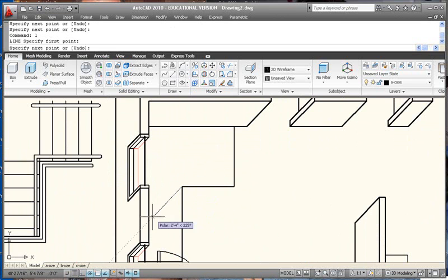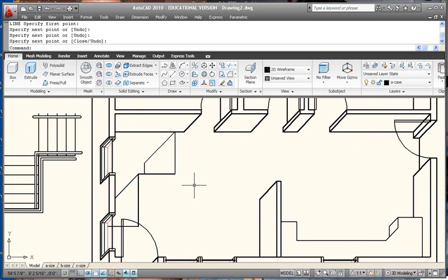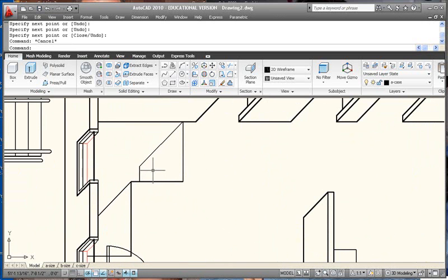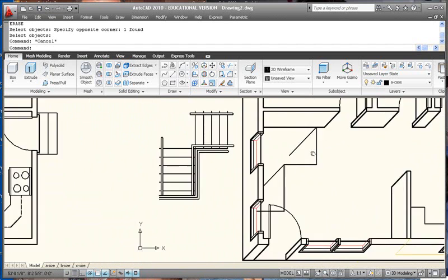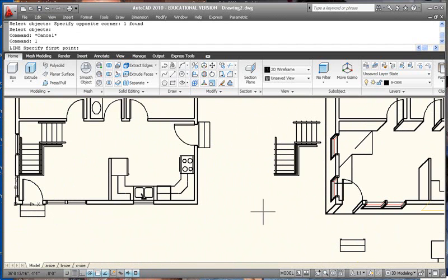So we're going to draw a line down like this because we're going to go down the stairs that way. And we're going to have another line here going down at a 45-degree angle as well. We're not sure where that's going to stop, so we'll just kind of do something like that for now. Actually, we'll just leave that open for now. Now, if we take a set of stairs and we draw them, we assume that the stairs are 10 inches deep.